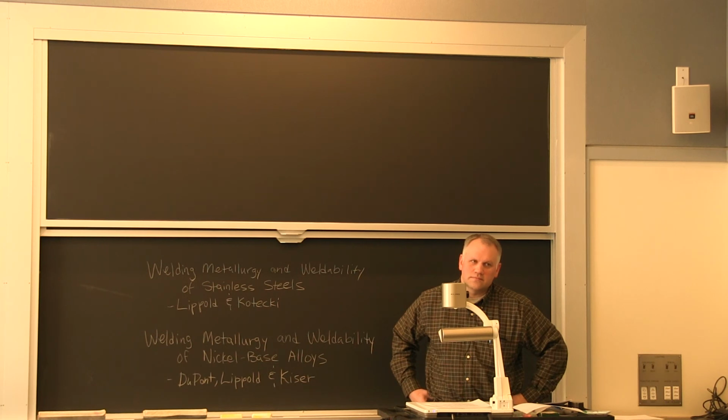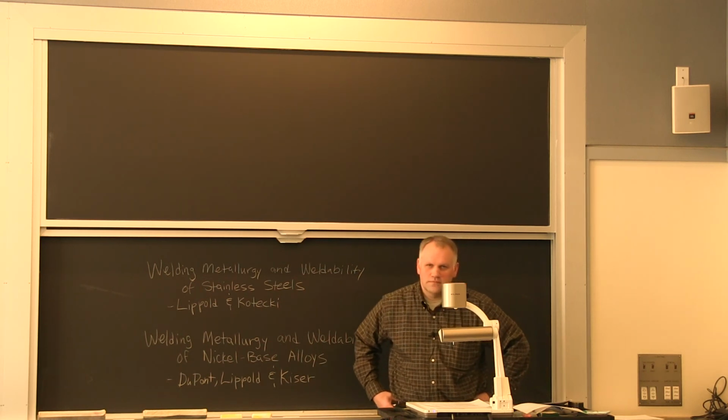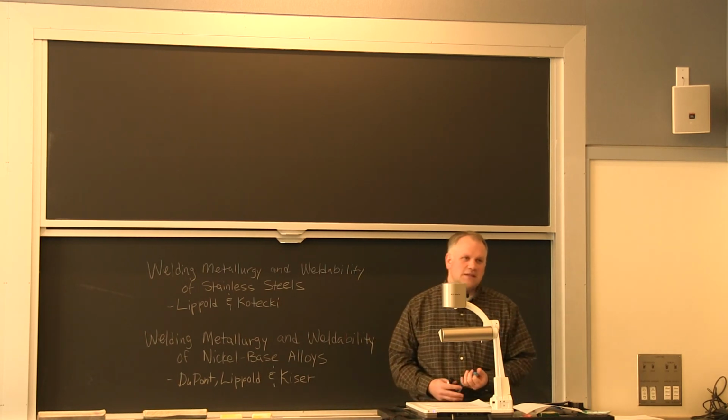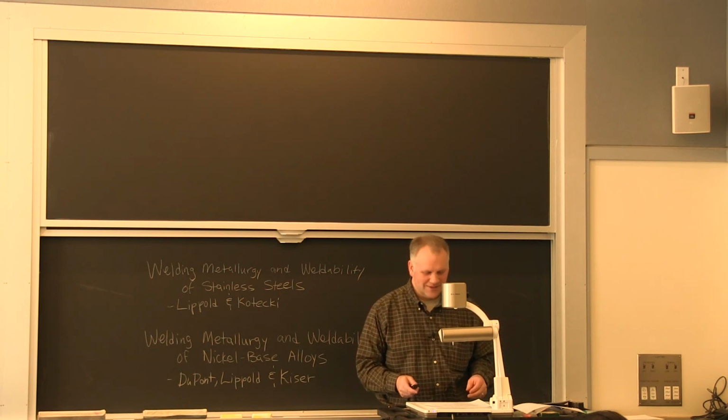Some things are plenty ductile but have low toughness. Silly putty is a good example. I can take silly putty and I can stretch it and stretch it and stretch it. Good ductility. If I pull it really quick, it snaps. That's low toughness. So there is a difference, but many people equate them. Okay, but there is a difference. Yes. I like the silly putty example. That's a good one.